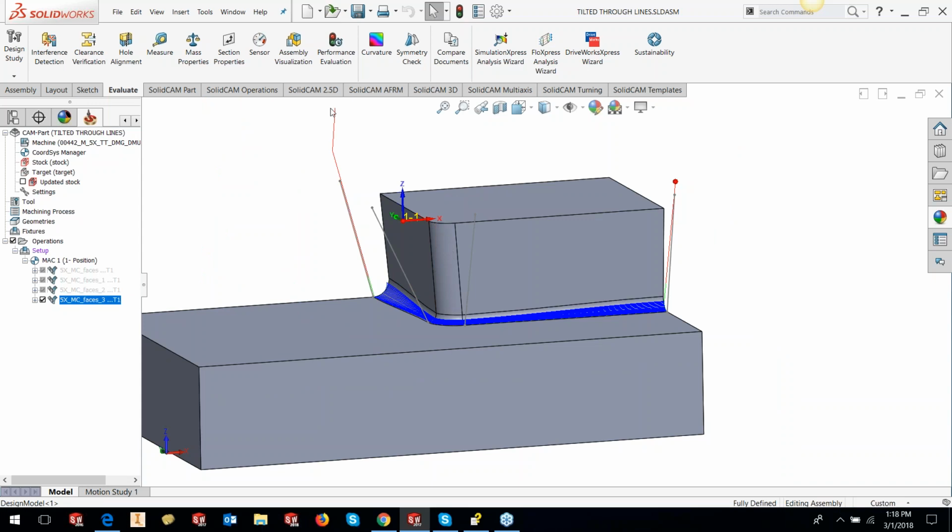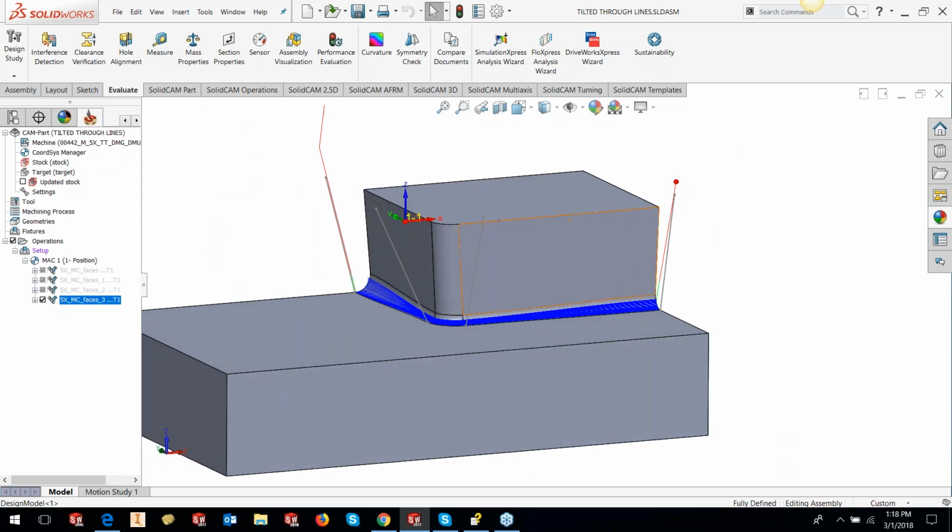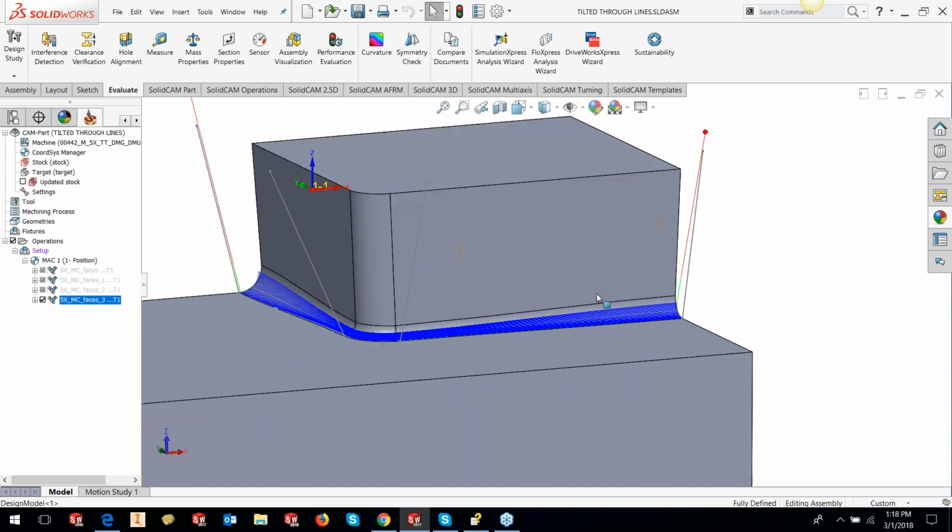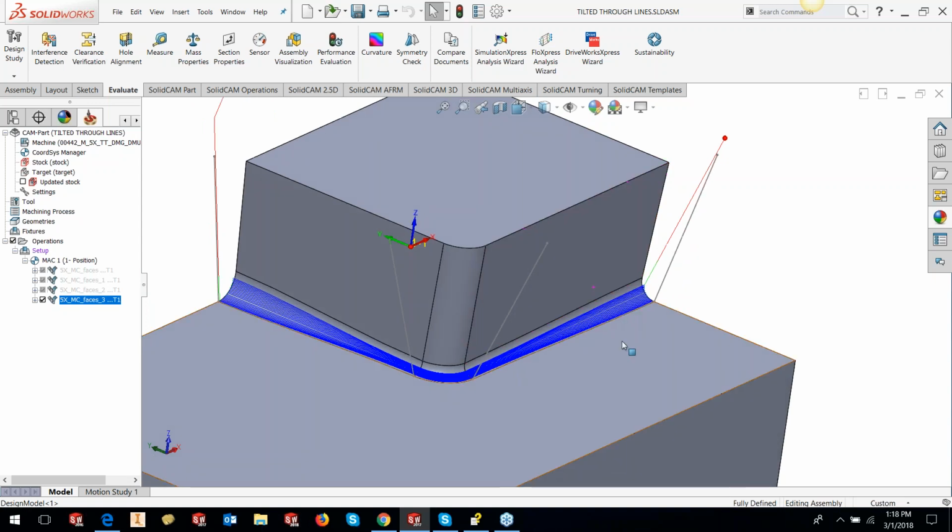So next time you get a part and you would like to pull the tool out in the normal or in the vector direction, then use this method and not the simple plane method or the cylinder method. You could also define 2 points. These are really safe approaches. Okay, so it's better than using a simple plane, right? So in our tool axis, we have now covered most of the items, what we did last time and what I showed you today also using lines.